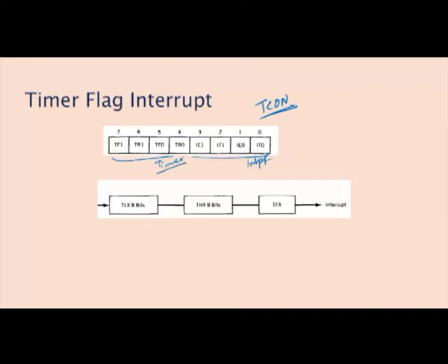Now we will discuss the timer. The timer also operates in 4 different modes. These modes define the size of the timer, that is either an 8-bit timer, a 13-bit timer, or a 16-bit timer. Now we are taking mode 1, which is a 16-bit timer. In the 16-bit timer you can use either T0 or T1; both are 16-bit registers, and both you can initialize with some value, from which it will start to count.